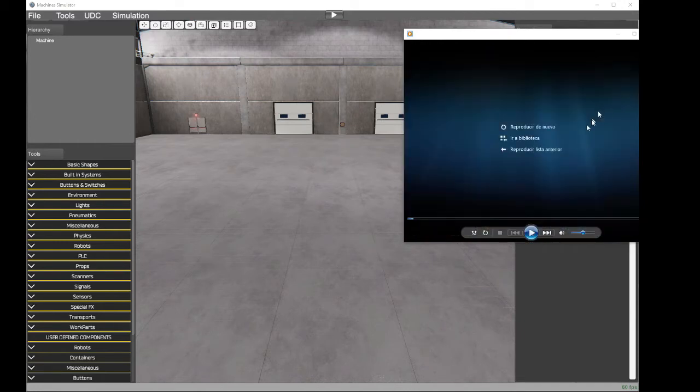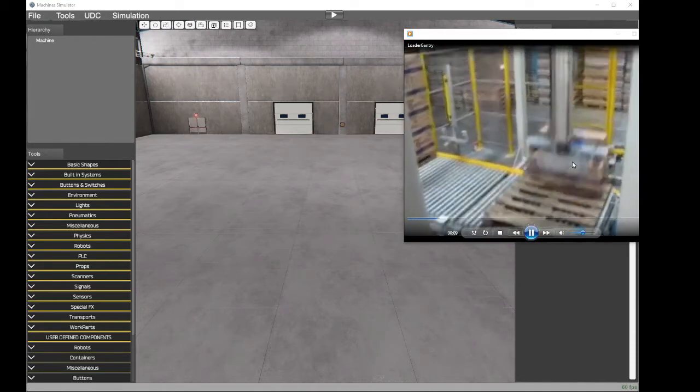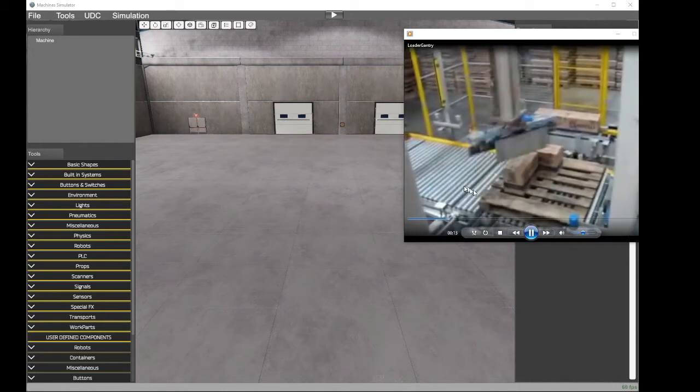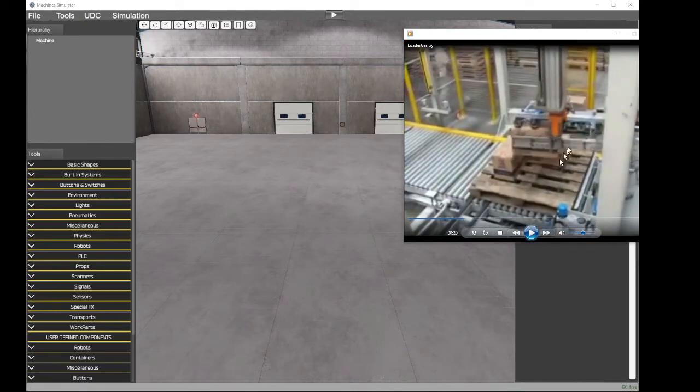We can see how there is a grip system that opens to let the box go, and then lets the other box go, opening the grip. The grip manages two different blocks to manage the two boxes separately. We see the gripper has a rotation system. We have the roller conveyor, also a transversal chain system to take the pallet to the load area, and another transporter for the boxes.